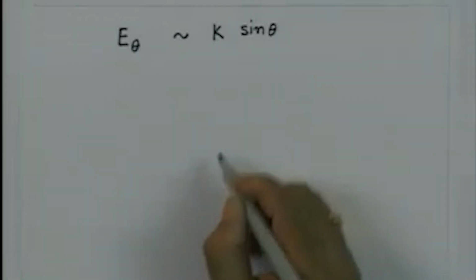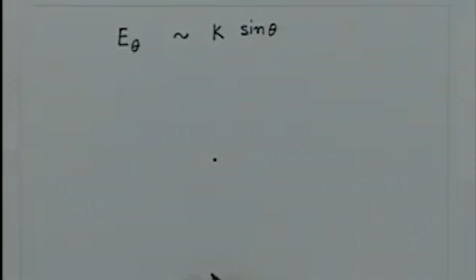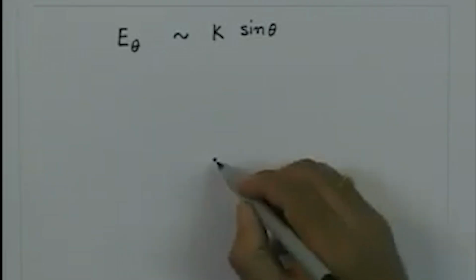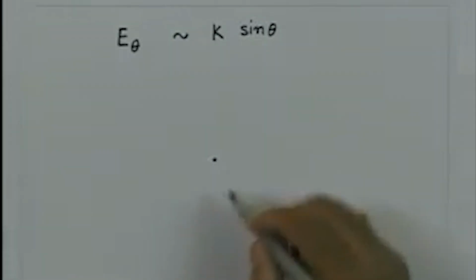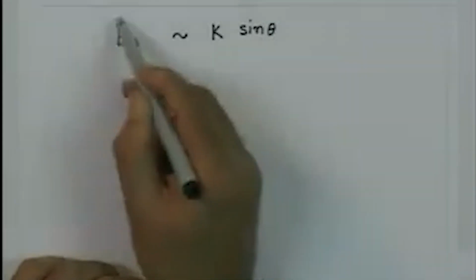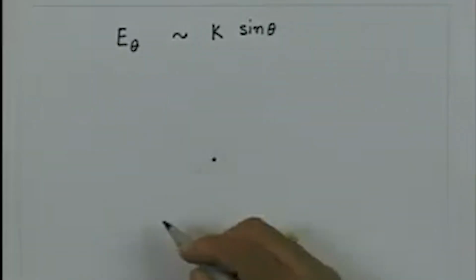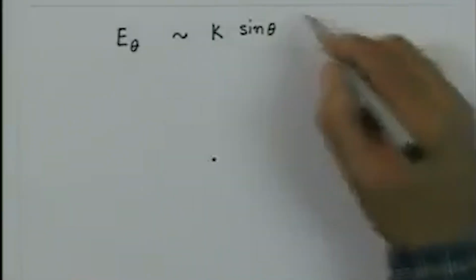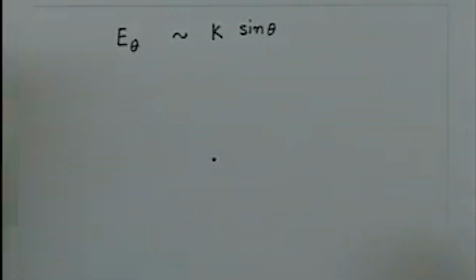Now if I consider this is the location where the Hertz dipole is located, and now the amplitude, not the distance, is telling me the amplitude of the electric field. So if I plot the electric field as a function of theta for only the radiation fields, then I will get this plot, which we call the radiation pattern.